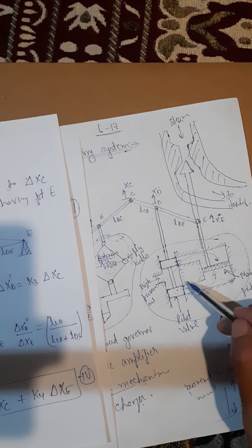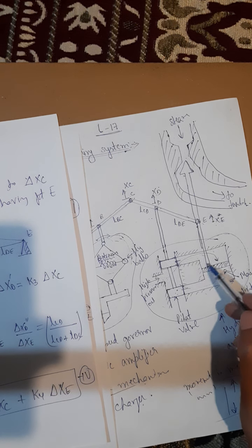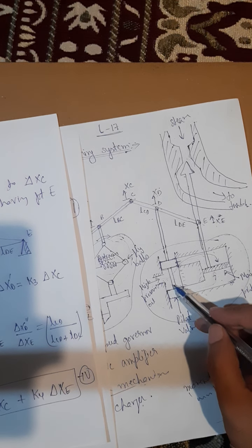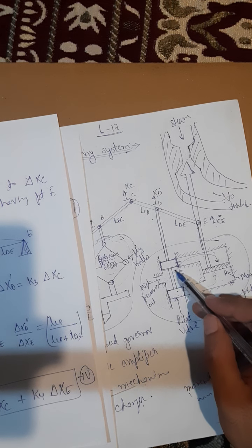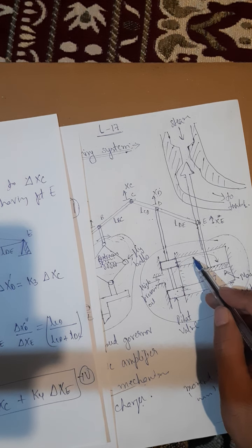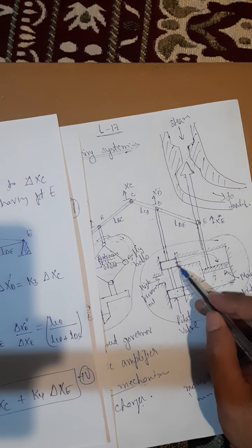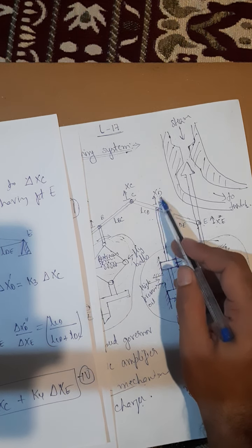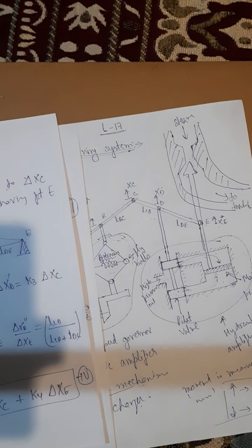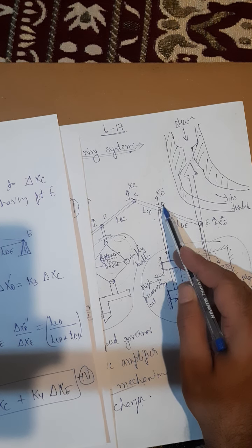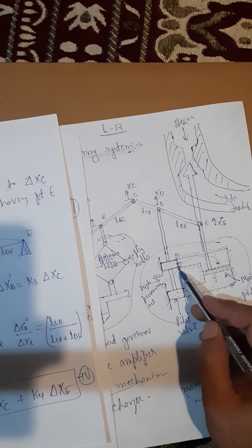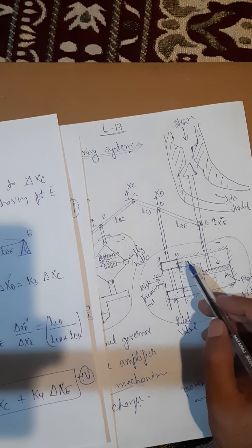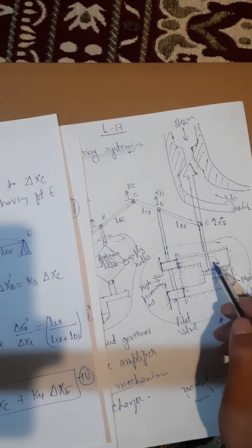Okay, and the second assumption is that, as a result of the first assumption where inertial forces are negligible, the rate of oil admitted into the cylinder, how much oil will enter the cylinder, will depend upon the port opening. How much this port will open depends upon the movement of point D, that is, how much the displacement of point D has been. So depending upon the displacement of point D, it will decide the rate at which the oil will enter into the cylinder.